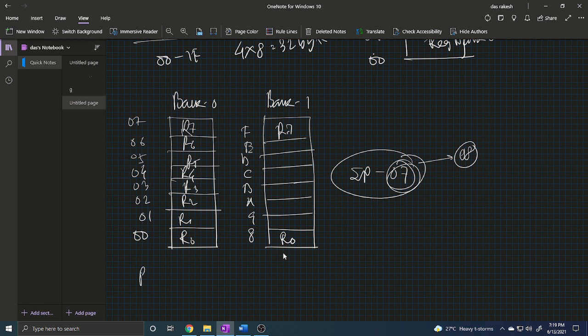So the first port is named port 0. It can be used both for input and output. And one thing should be remembered, this is very important. Okay, please write down. When the P0 pin, port 0 pin, is used, then this pin must be connected externally by a 10 kilo ohm pull-up resistance.